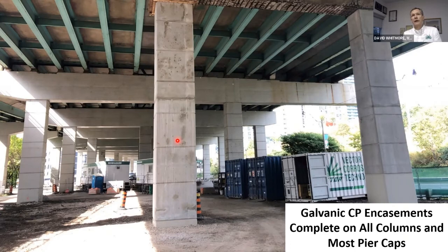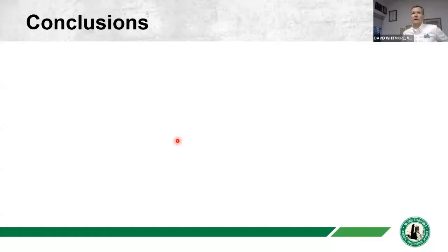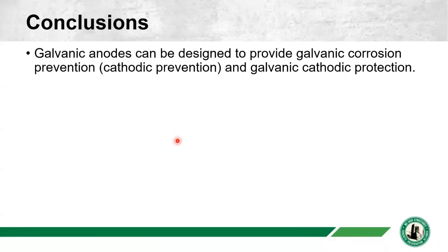And so it's a way that they are able to repurpose the substructure and able to do the rapid bridge deck replacement without shutting down to traffic for an extended period of time. All the work on the deck is being done at night, and there are no complete closures during the day on the upper portion. So just to kind of wrap up, David, I might just quickly.